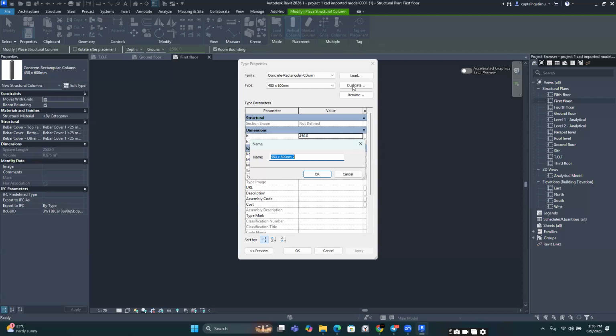So we are now doing column 3. I'm going to change the name to column 3, and then provide the dimensions. So we always provide the dimensions so that it is in the name so that it's easier for you to identify the columns. All right. So as you are working, you don't have to go probably measure them, click them to see what family is used.